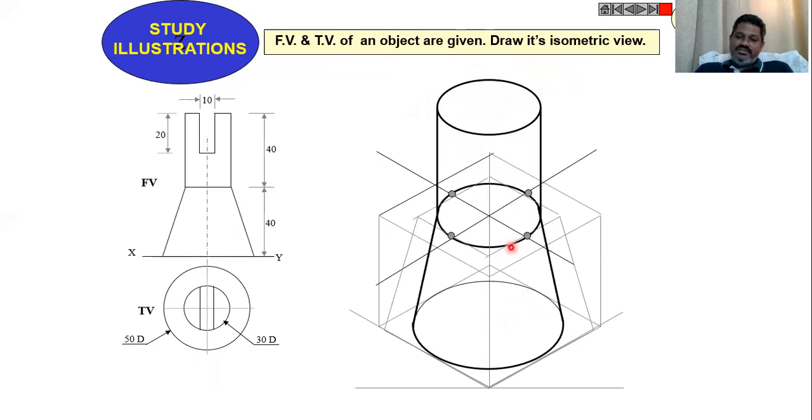On the bottom, we have the frustum of the cone, on which we have the cylindrical surface. On the top of this cylindrical surface also, we have one slot that we need to locate. Then get the distances. Exactly take the midpoint and from the mid 5 mm and 5 mm and come down for a length of 20 mm. Then draw an arc here, which gives the complete figure of the isometric view for the given compound figure.